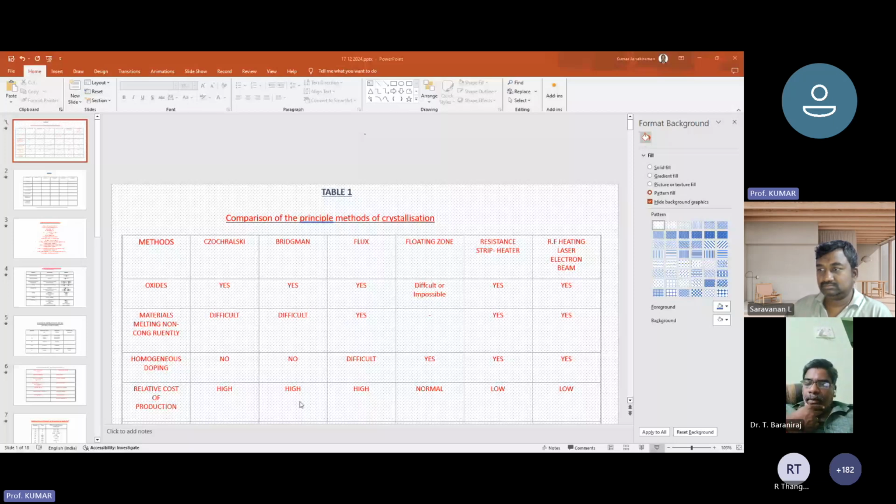Generally, people use scanning electron microscopy in order to understand the surface and then use its properties. So, for example, once a crystal in a cylindrical form is obtained, the diameter is generally, as I said, about 2 inches when we started crystal growth in 1990. And then subsequently, the seed was oriented with 100 for very specific purposes. As I said, the attachment energy of the subsequent epi layers is very good if you use a 100 layer, and therefore both ends are cut and then the surface is oriented.